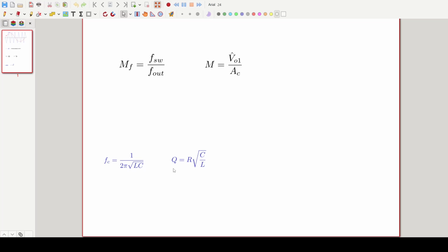Also in antennas, it is a value which is very common in the electrical engineering world. For our parallel RLC circuit, the higher the resistance, the higher the Q factor, and the higher the Q factor, the more energy is exchanged through L and C. So basically this factor tells us how well our filter resonates.